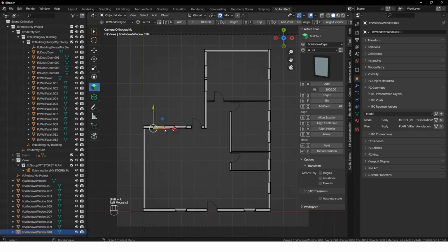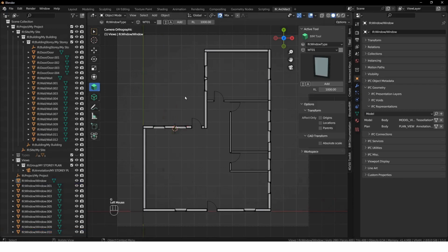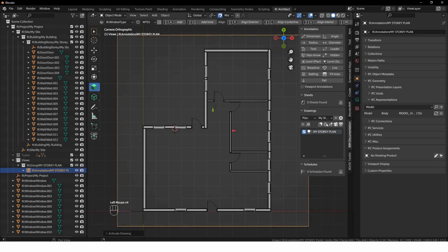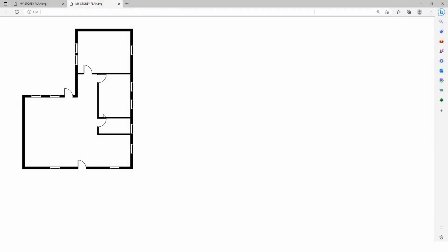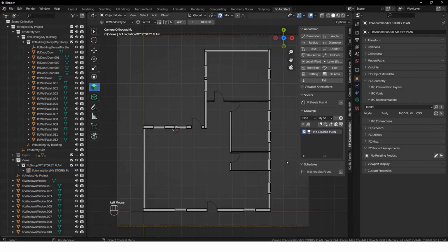And then these two I want to be on the outside again, so I'm just going to select them, say GY, and snap them to the top, and there it's sorted. So then we can just go to BIM documentation, we can activate again, and you can see it's changed to the 2D representation of the windows as well, and we can say create drawing. And there you can see we've got door swings and the windows in. Okay, the next thing we want to do is add our furnishing elements and just fill up the scene.